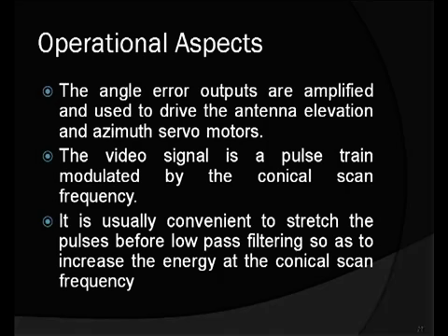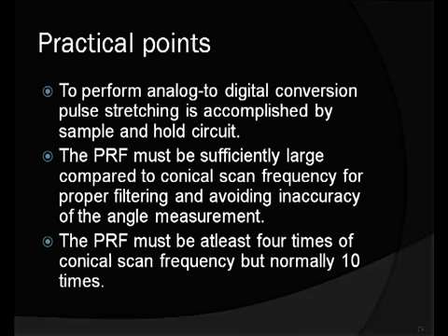It is usually convenient to stretch the pulses before low pass filtering so as to increase the energy at the conical scan frequency. To perform analog to digital conversion, pulse stretching is accomplished by sample and hold circuits conventionally. The same technique is being used here also.